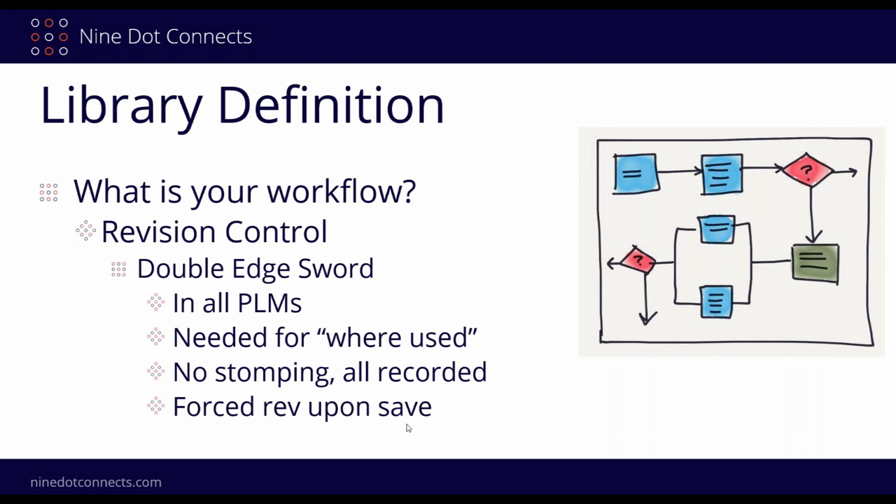So if you think about it, especially in Altium products, if you're working on a project, and I was thinking about this the other day, I thought it was kind of fascinating. In Concord Pro or Altium 365, if you do save it, you bump the rev. However, if you're working on a project, you actually have two revision control systems in play. One of them is Git, which is off to the side, and as you're going along and working on your project, you make the decision to push it into the revision system. And then when you're ready to do the formal release, you push it into Concord Pro or Altium 365. So they give you the option to do a bunch of saves before you ultimately push it into one of those two systems.